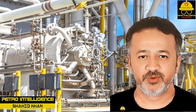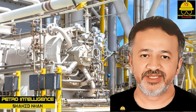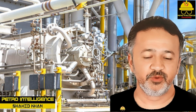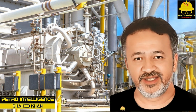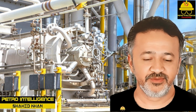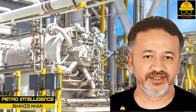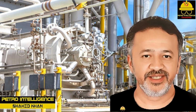The compression ratio normally runs in the 3 to 4 range, with the same approximate compression ratio in each stage. For example, if the desired discharge pressure is 1,500 psia, a 4-stage compressor with a 3.2 compression ratio in each stage might be used. The pressure at the discharge of each stage would be: first equals 47 psia, second equals 150.5 psia, third equals 481.7 psia, fourth equals 1541.4 psia.